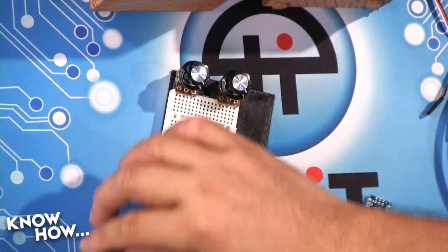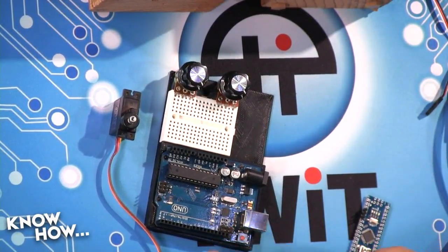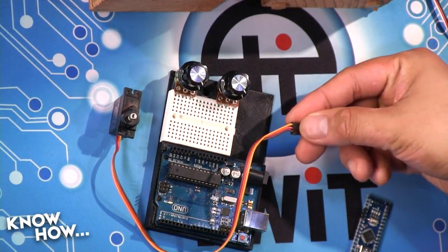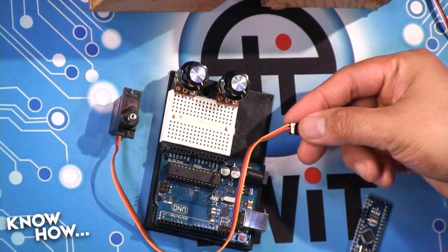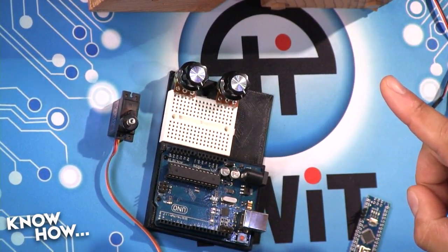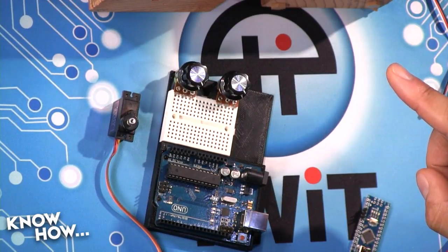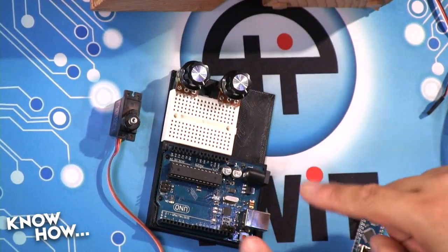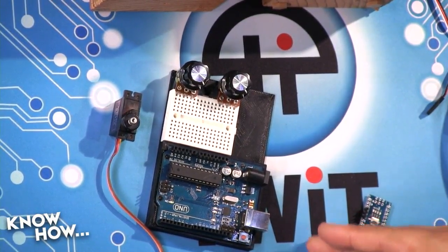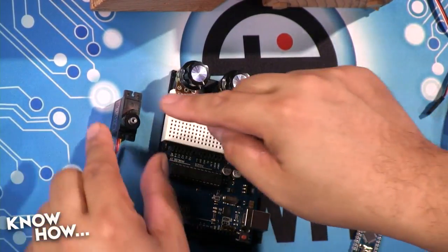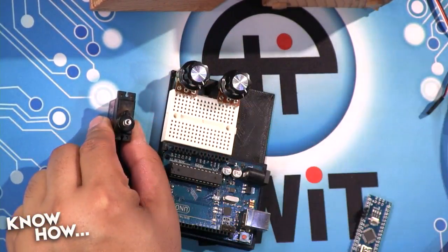So here's what we're going to do. If you go to the overhead, this servo is going to need power, so it means ground and voltage. And then it's also going to need signal. It needs the digital signal that's going to allow the PWM signal to tell the servo where it should be. Right, like all our other projects with the LEDs. Precisely. And what the servo is going to be listening to, and in fact what the ESC is going to be listening to, is how during a particular clock cycle, how much is it on and how much is it off. And then it's going to turn that into a value for where the servo is pointing. Very cool.